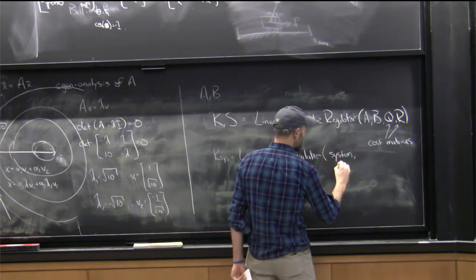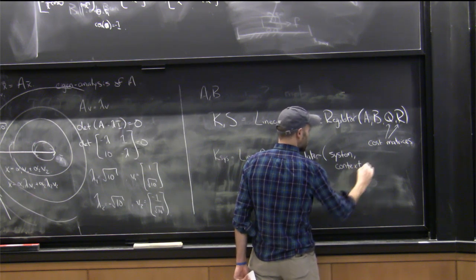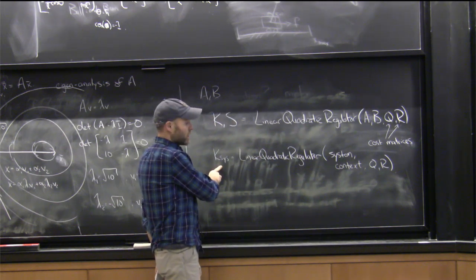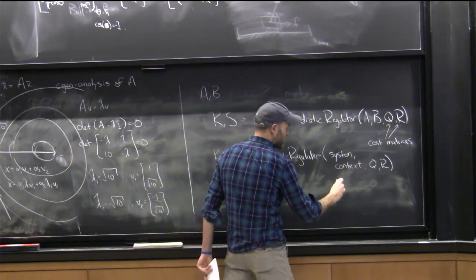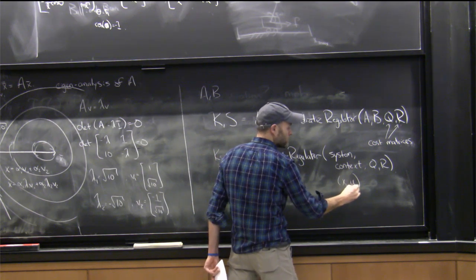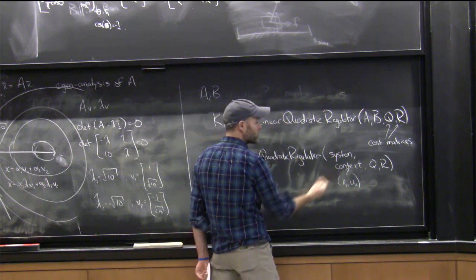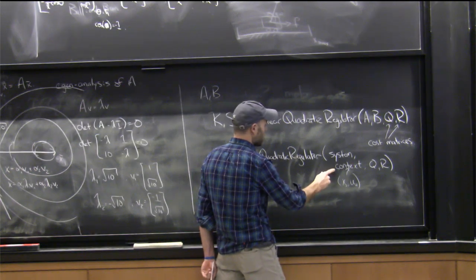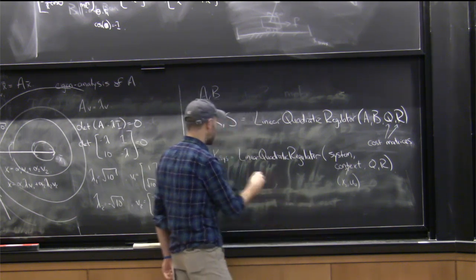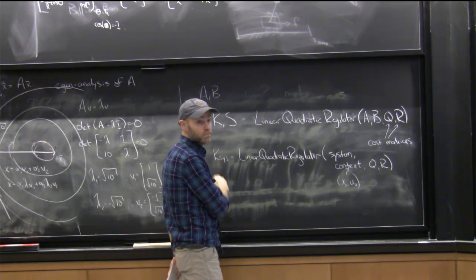I don't know if you've yet come to terms with this, the fact that we call this thing the context, and then QR, and it'll spit out a system like this, okay? The context is just a summary which has X and U, so it's capturing X naught and U naught. It also has parameters. It's everything you need to be able to run a simulation, okay? And you can just call it like this, and it'll linearize the system for you, and then call LQR and return even a system that you can use in a simulation that implements the linear feedback, right?